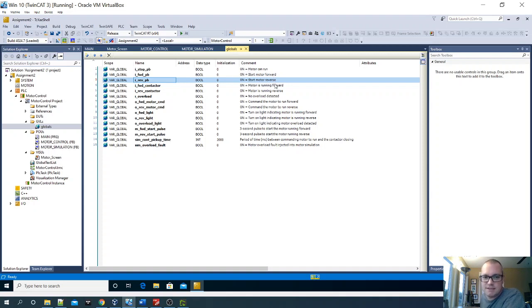Although, in most cases, if I just said stop push button normally closed, you'd probably be able to figure it out. But anyway, this is how we did it. So this is how I'm used to doing it, and this is my preference, because it just makes it completely clear to everybody exactly how each I/O point is working. Okay, so we've created those I/O points to begin.